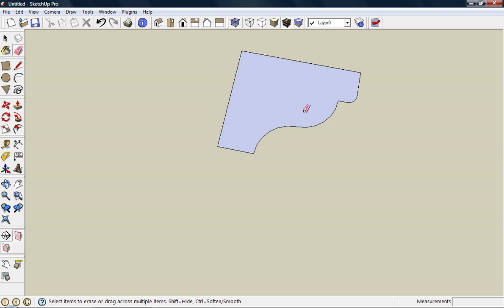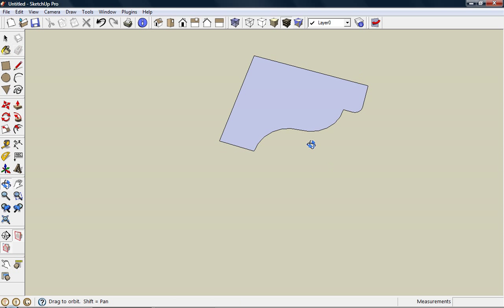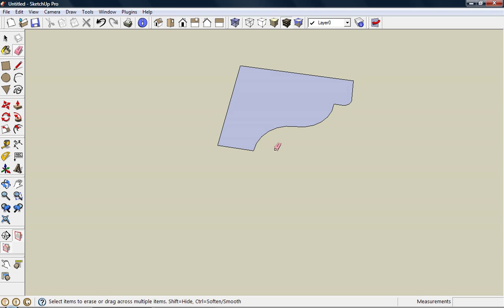Now this new face can be used as a profile and turned into moldings when we move into 3D. It can also be rescaled and used more like a router bit to put an edge on any piece of stock we choose, like a countertop or even a mantel shelf. The best part is that now that we've gone through the process of making this, we can save it and use it in any of our future drawings.